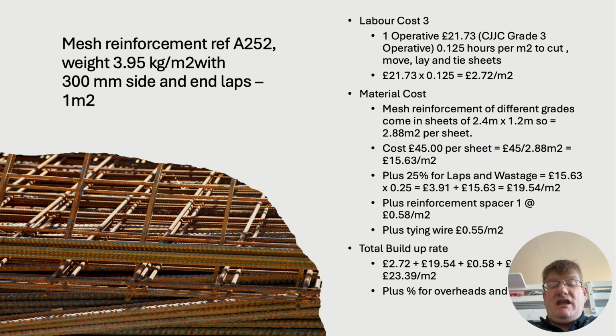You need spacers. You need tie-in wire, and again, I got all of that off the internet, to be honest with you. The spacers are what the mesh sits on. The concrete, obviously, has to sit on something, otherwise it'll be on the floor, and that's no good for anybody, as you can imagine. So I've added that into it as well, a little bit of sundry items, just to give it that degree of accuracy.